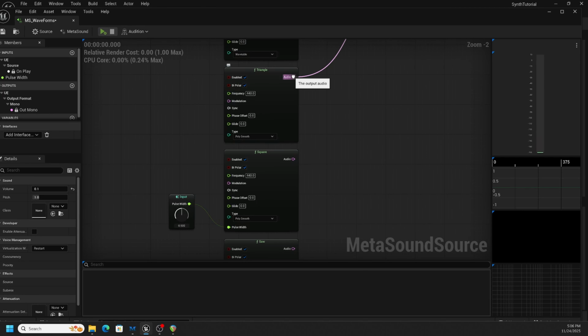Now this one is going to seem significantly brighter, significantly louder. Psychoacoustically, it's going to seem louder than the triangle wave. And it only generates odd harmonics, again, just like the triangle wave. However, they have a lot more amplitude. The harmonic content of the square wave is significantly more robust, and that's going to seem brighter here into our ears. It's going to seem louder.